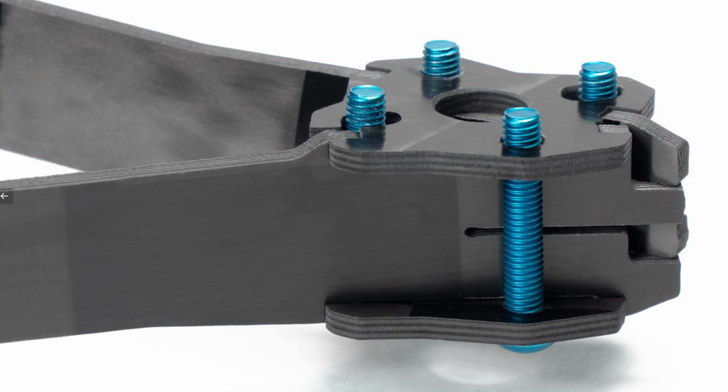Exactly. Because as you saw in the list of carbon fiber, when you're going up in stiffness, you lose strength. And when nothing flexes, your forces will get huge. So that's why we had to make a frame that is several times stronger to compensate for this, because otherwise it will fly great, but it will be really brittle when it crashes. So actually, the first prototype flew really good, but it was very brittle. So that was actually what we have been fixing.